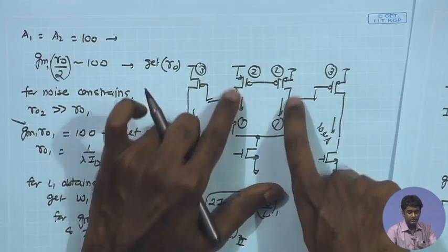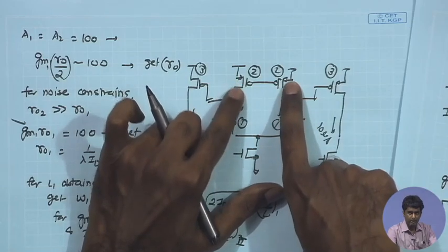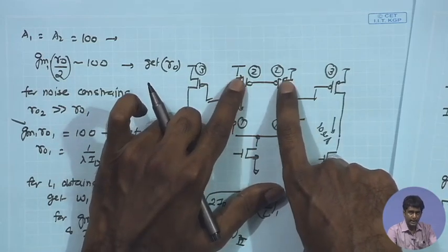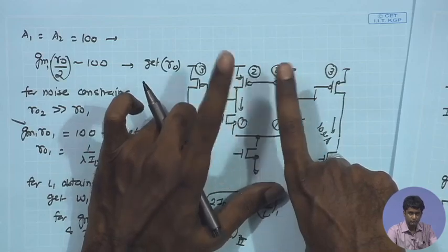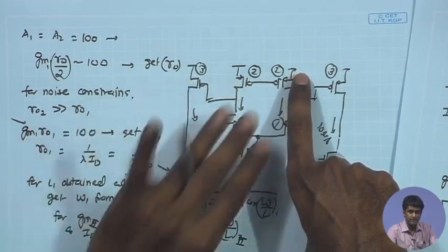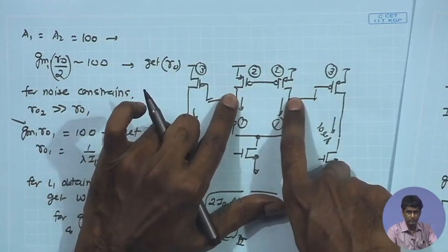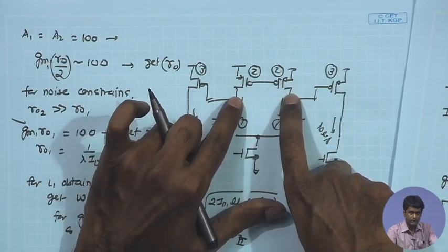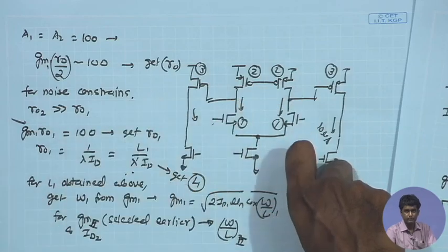and the next is the W and L of this. So, as we said, the L of this device can be increased, we can try to push the L towards a higher value, and that will help me in reducing the 1 upon f corner frequency towards a lower value. What is the possible disadvantage of that at the first stage?